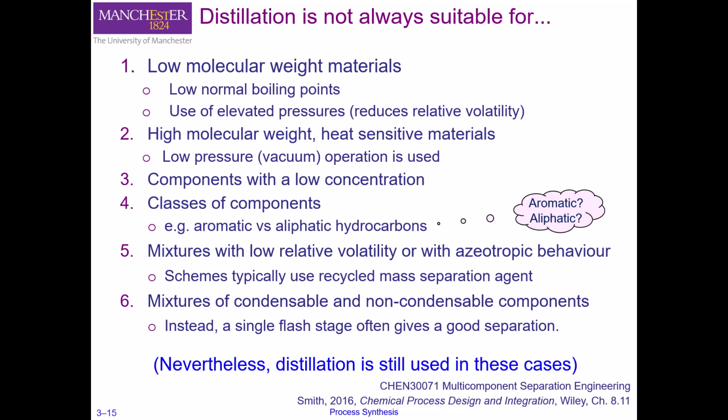This large flow implies that the equipment would be much larger, because it needs to handle that reflux. But also the heating and cooling of that circulating material could be very expensive, because the bigger the liquid flowing inside the column, the more vaporization you need to provide. So it means a bigger reboiler, and also you need to do condensing, so you have a bigger condensing heat duty as well.